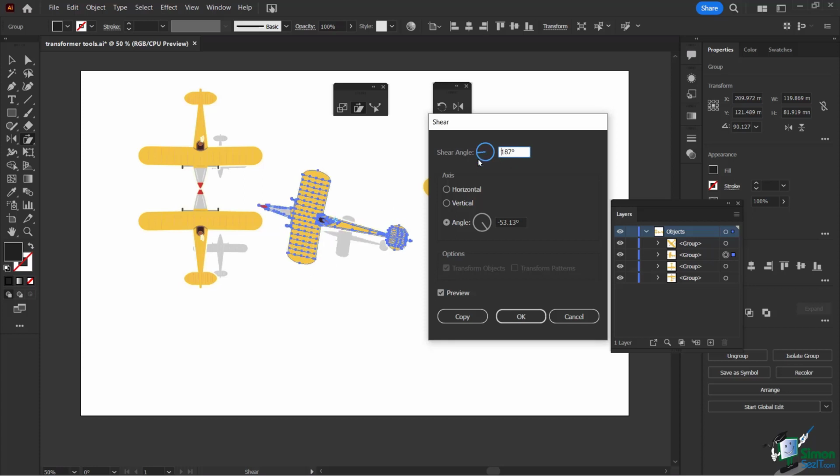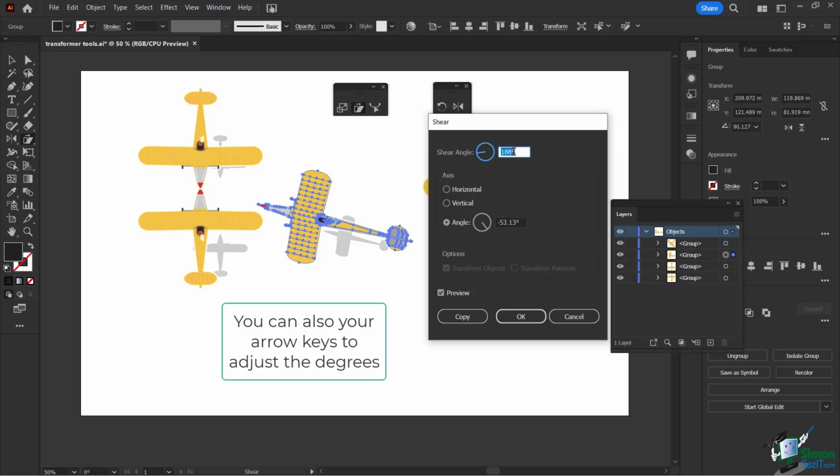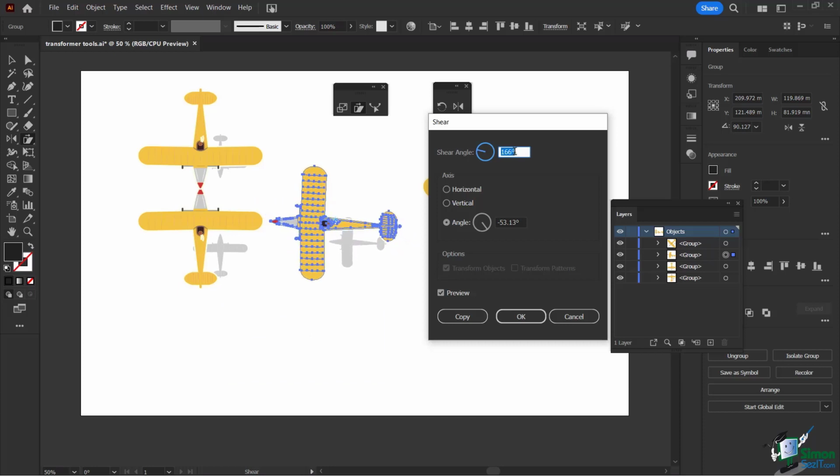Now, if you want a real-time preview, click inside of this box where the degrees are, notice my cursor is in there, and use the mouse wheel to incrementally resize it. See that? Pretty neat. I'm seeing it in real time, so I know exactly what I'm going to get as I'm getting it. When I click and drag on this, I have to wait to release the mouse to see it. All right, so cool. Now that's the effect that I'm getting.